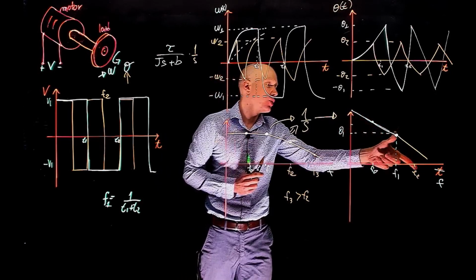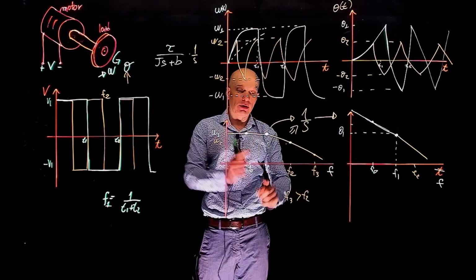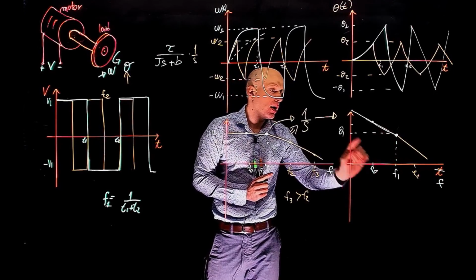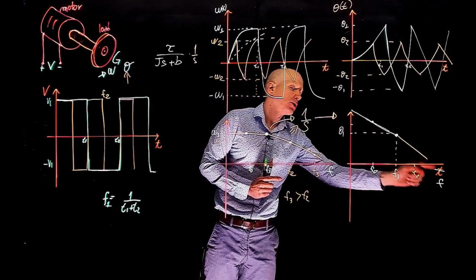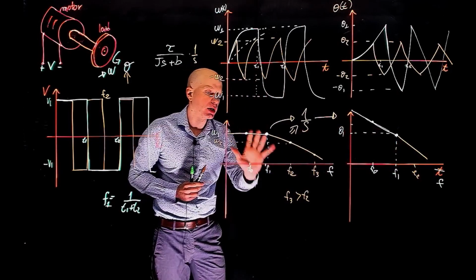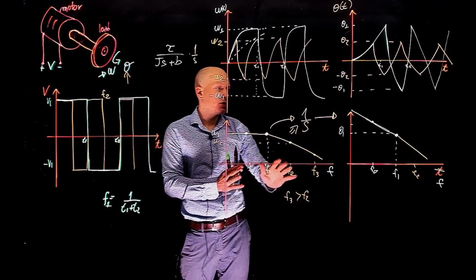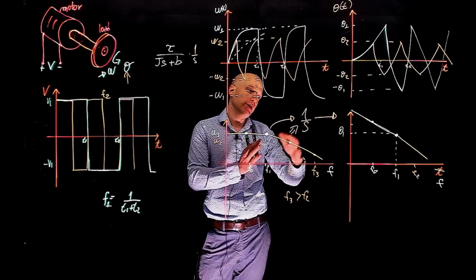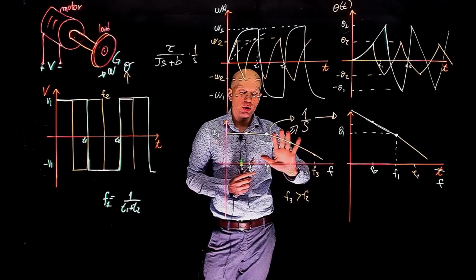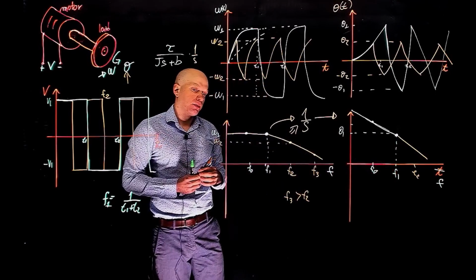This slope just increased. It increased because we had the effect of the inertia and friction that resulted in this cutoff frequency, which is again there, but now in addition we have that slope created by the pole at the origin, which is the integration reflected there. And this now represents the Bode plot, or something that could be a Bode plot with further manipulations, which is the frequency response of this particular system.